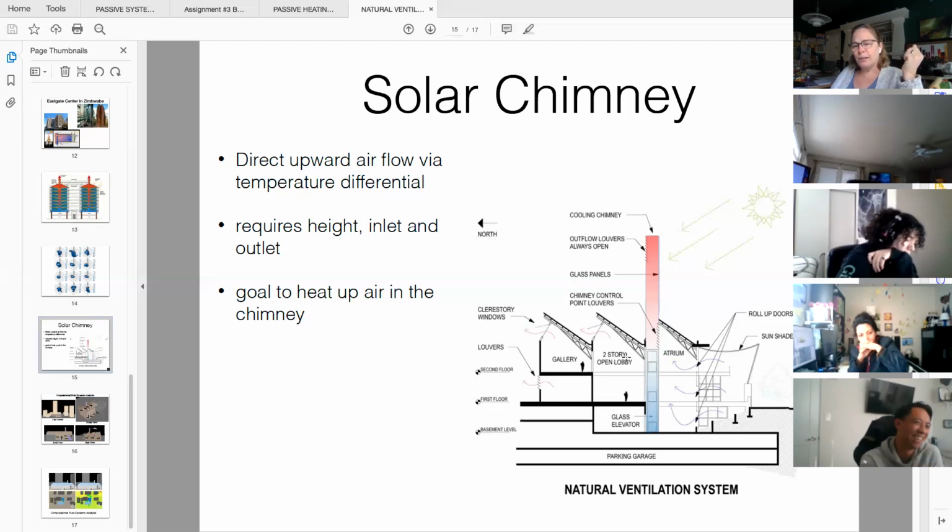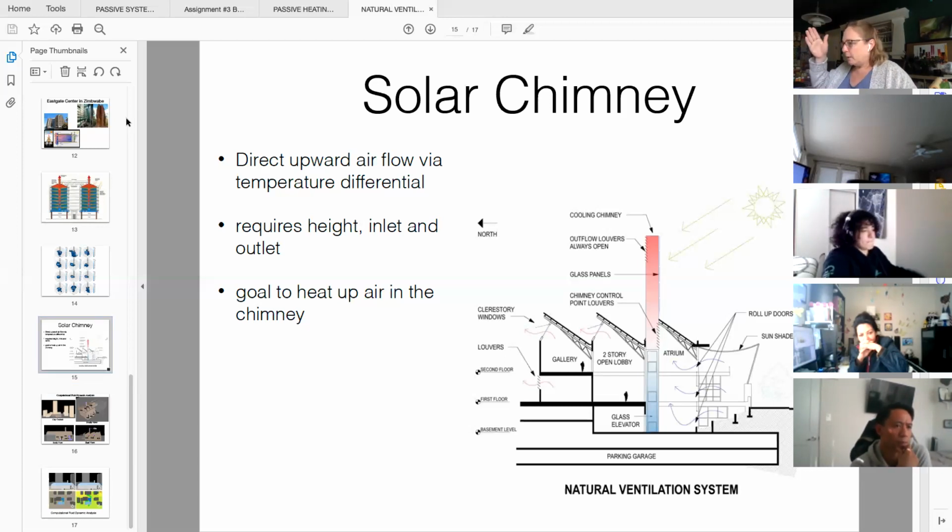Brandon, you're looking very puzzled. Yeah, I'm sorry. So you close the doors, and you don't have to close the chimney or anything because the pressure in the hot air takes in that cold air from the flow. Yep, exactly. So the louvers at the top of the chimney are open 100% of the time. By closing the incoming air, you're stopping that process and just cutting that circle off. I see. You're just not putting any input in it for that system to work. Correct. Exactly.